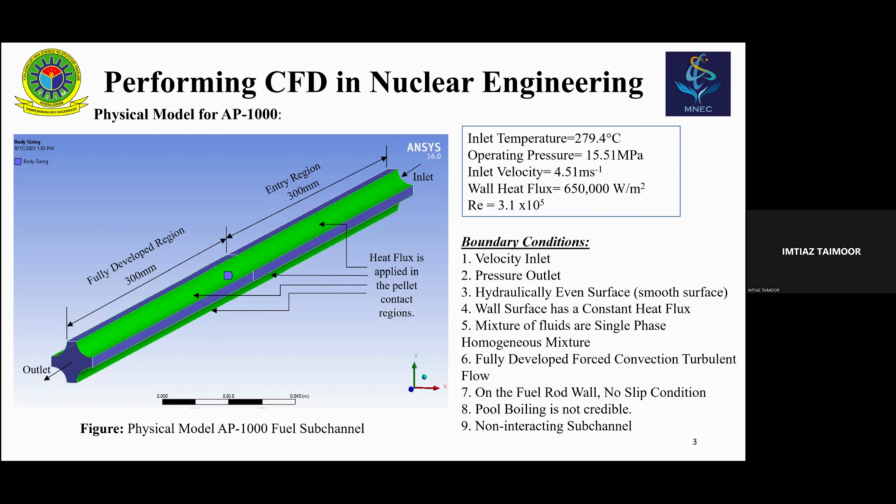And for the different operations in ANSYS, like what operations you have to choose, or step-by-step guides, you will find all these things in different tutorials. But these theoretical things you need to match with your ANSYS procedure. So you need to give a length that is enough for full development of the flow.